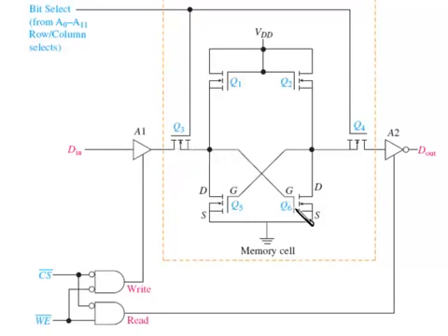When Q6 is turned on, it's essentially a short from ground to this point. This ground is fed back, kind of like the cross NAND flip-flop that we looked at earlier in chapter 10, which turns this transistor off, which essentially is like an open. Q1 and Q2 are just providing the bias necessary for their corresponding transistors. So with Q5 off, current will be allowed.